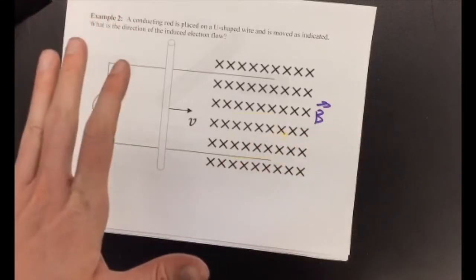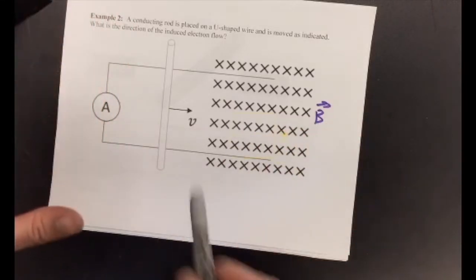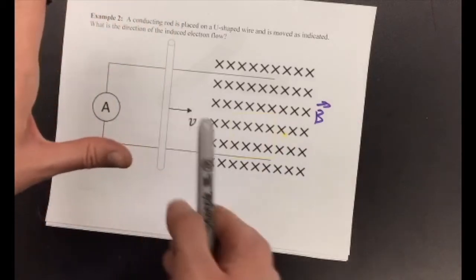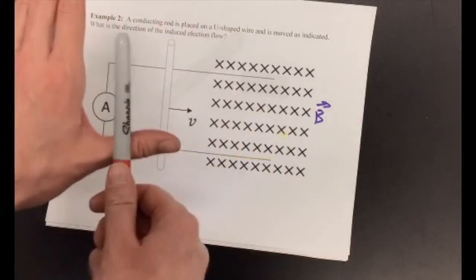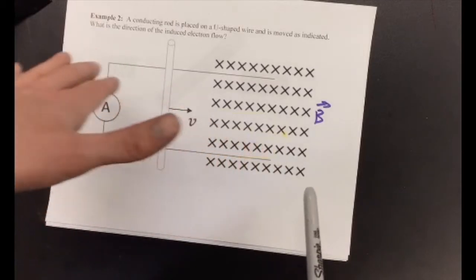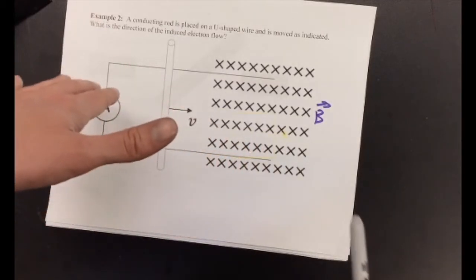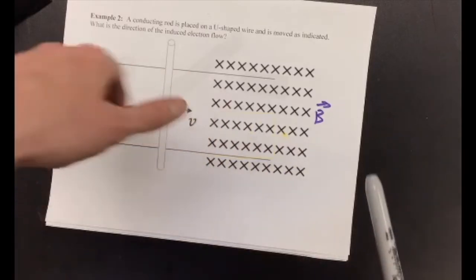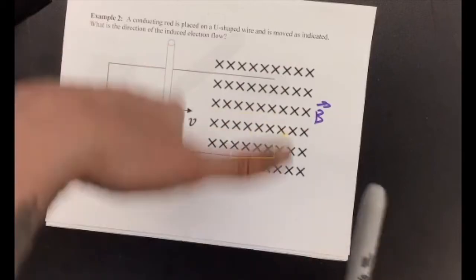So electron flow. This is going to be our left hand rule. So let's take our left hand. We're going to point our thumb in the direction that we're going to make those move first, right? The conductor is going to get pushed that way, which means all the electrons in there are going to get pushed that way. We have a magnetic field into the page. And so when we cause that motion, what force are they going to feel? If we make them move that way and the magnetic field is into the page, electrons are going to feel a push down towards the bottom of the page.